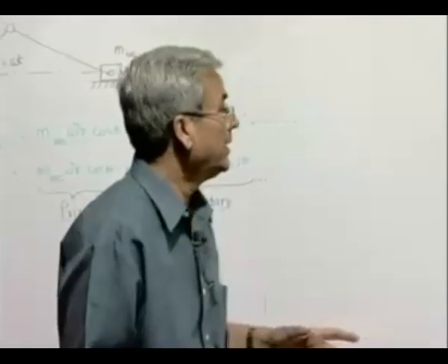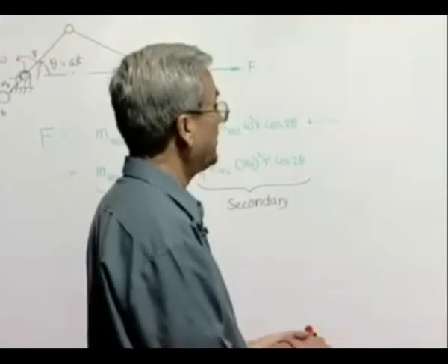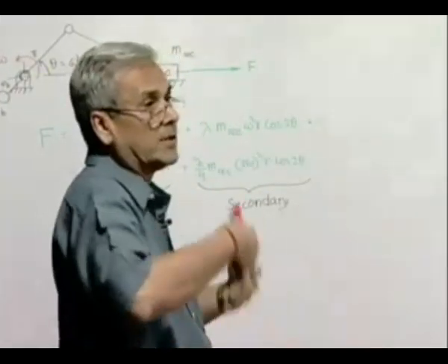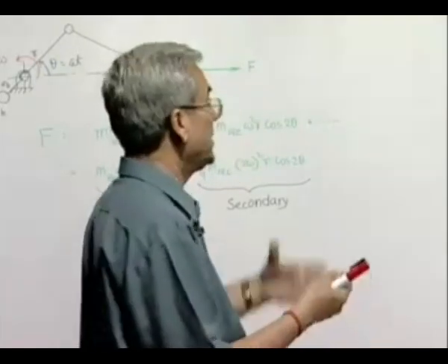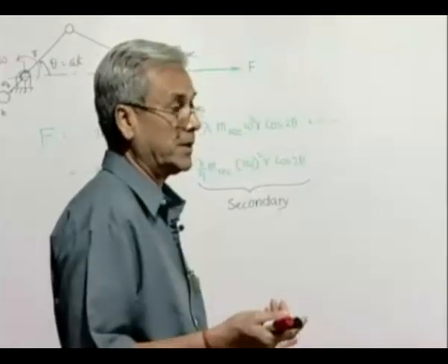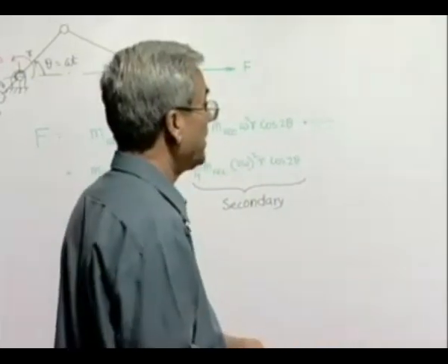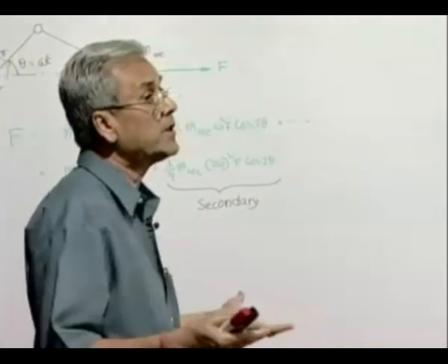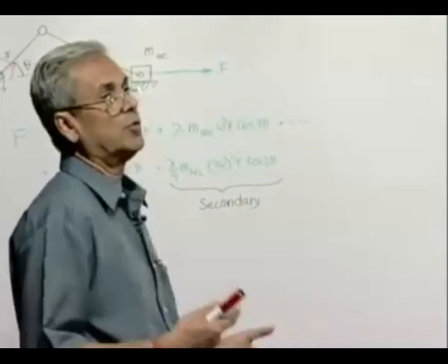If we find that those reciprocating masses M, if we put them at the crank pins, balance among themselves, then obviously any component will also get balanced. That means the real unbalanced force also will be balanced. If the moment produced by these hypothetical masses at the crank pins is 0, then the component of the moment which will actually be there will also be 0.